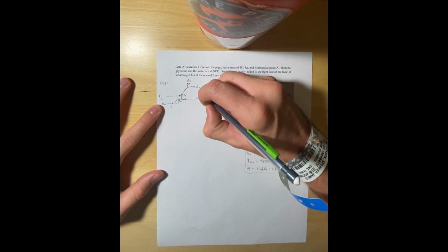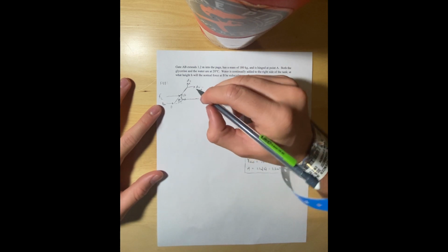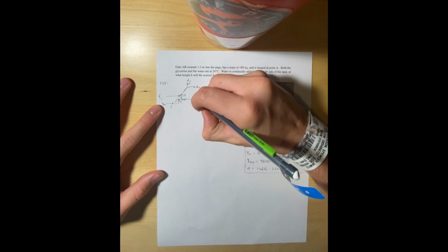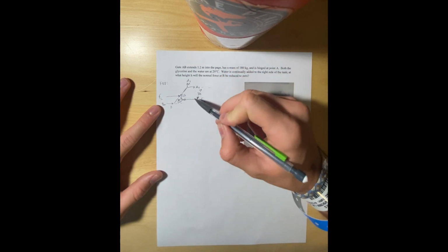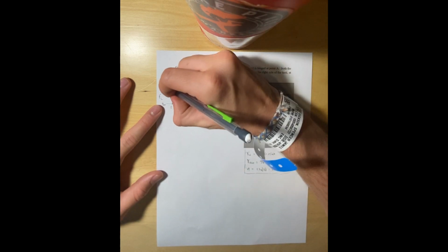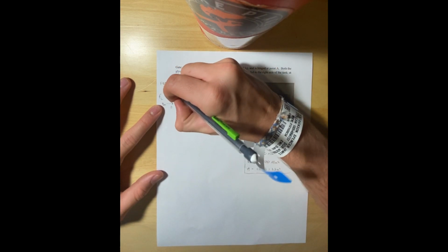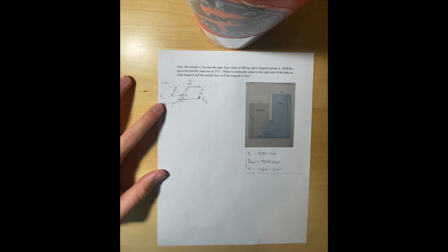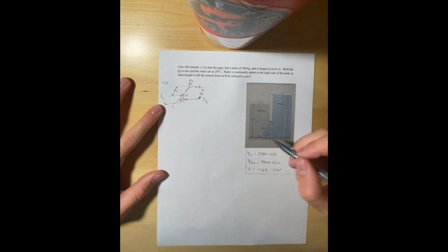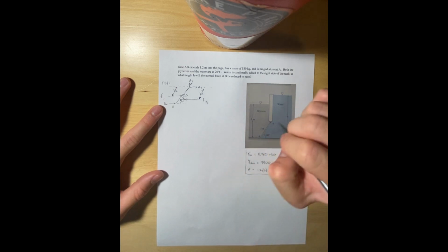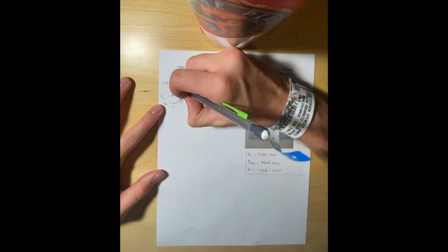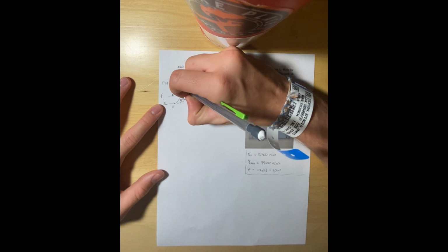So this distance right here is going to be our y sub r term. And that's just the distance from point A to where the force is acting on the gate. And then this term is going to be our y sub L. It's the same, just on the other side. All right, so now that we got our free body diagram down, we know that the gate is 1 meter long. So we're going to go ahead and say that this distance is 0.5 meters. And from there, I think we can start the setup of our problem.